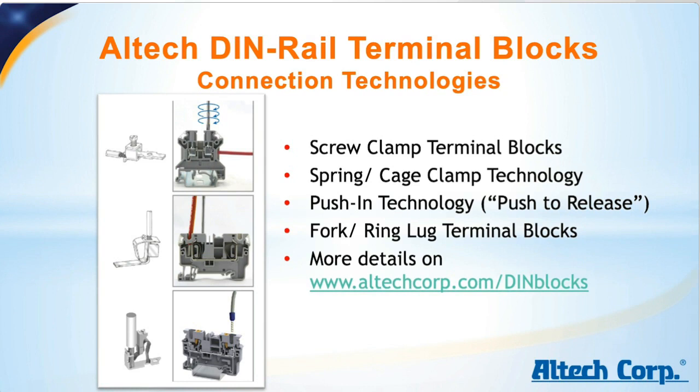Now the push-in technology, as the word push-in already says, just by using the force of the conductor, you generate pressure on a spring, which is usually made of a high quality stainless steel material. You open that spring automatically, and just this way, by pushing in your wire, you make a connection. You do not need any tool or screwdriver for that if you use a solid conductor or you have a wire with a ferrule on it.